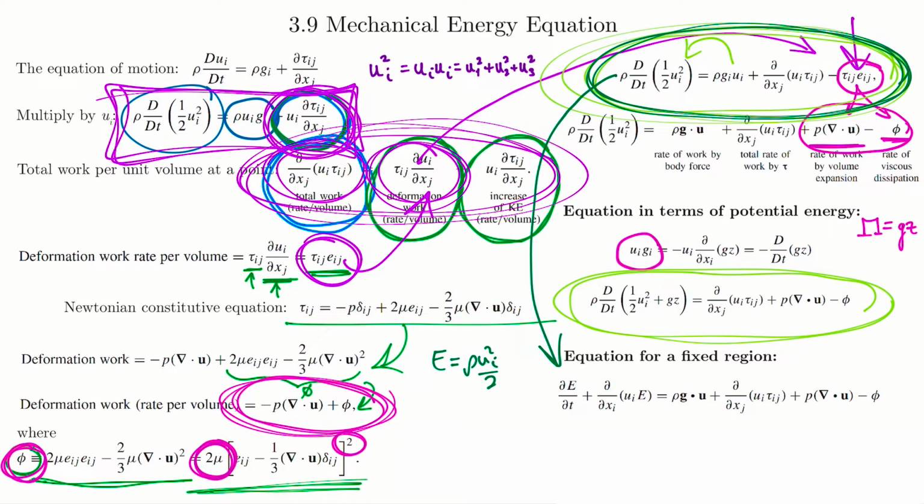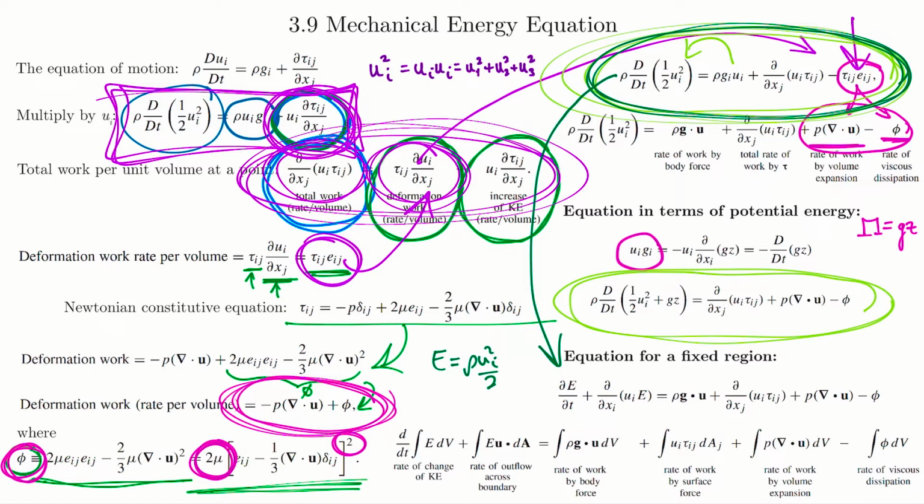So we integrate each term of this equation over our fixed volume V. And another trick we've done before, right? The second term and the fourth term are in a flux divergence form, okay? So that when we do their volume integrals, we can change those into surface integrals by Gauss's theorem, okay? And then we rewrite the complete integral form as I've shown at the bottom here, where each term is a time rate of change. And I've also listed here how we can describe each of these terms.